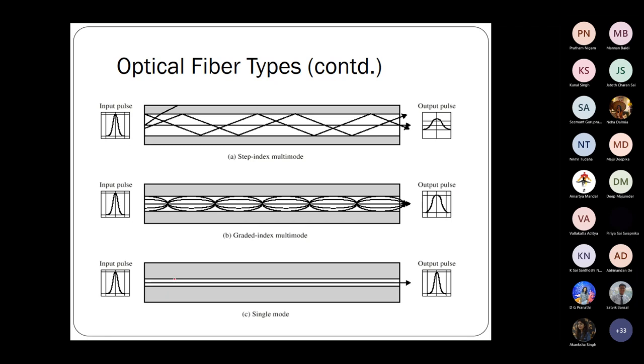So you see, if you make this very thin, the light will go almost straight. This is what is called a single mode fiber, commonly called SMF. Don't worry about this two graded index one. Let's just try to make this slightly better. But if you are putting a light out here with multiple paths, then these multiple paths will take different times to go. So then I will again have a delay distortion out here.